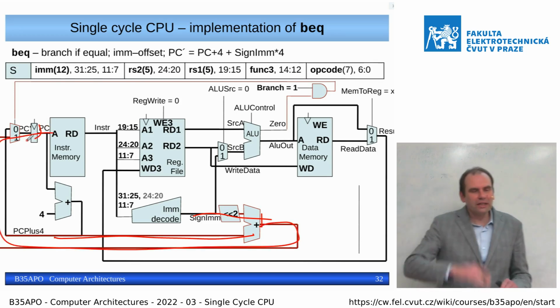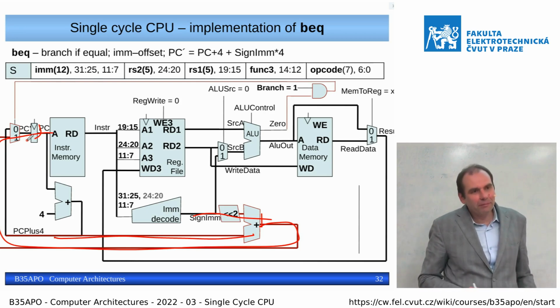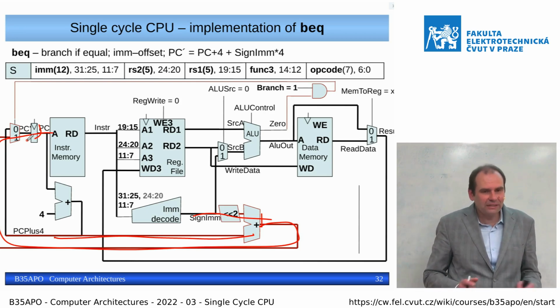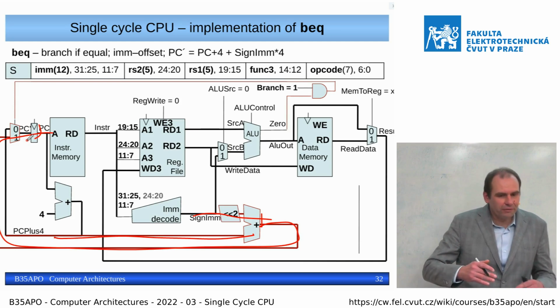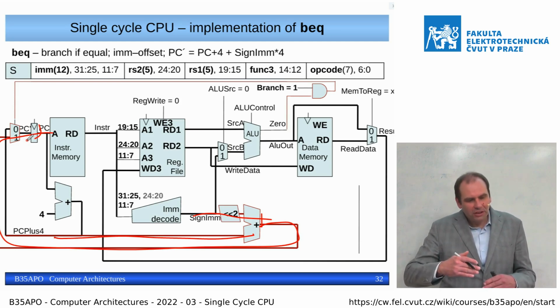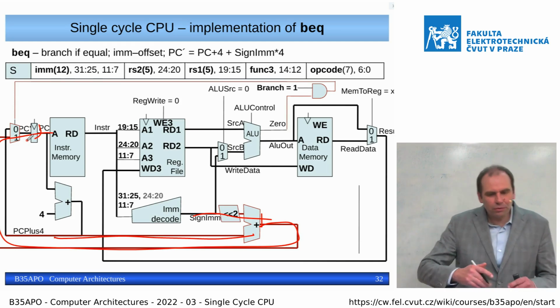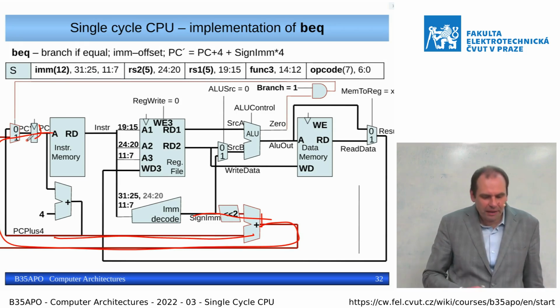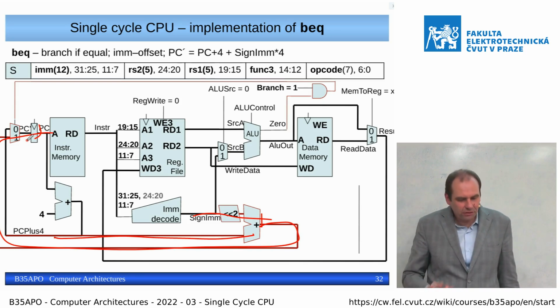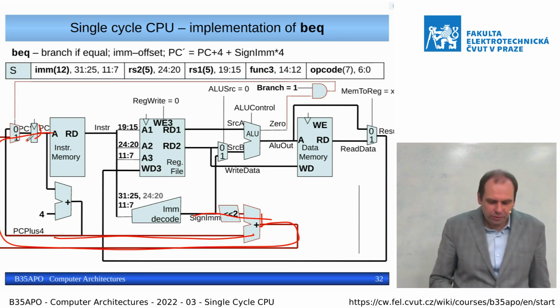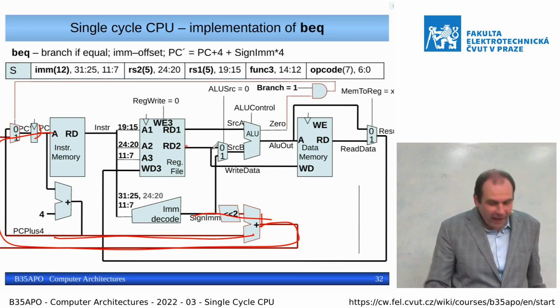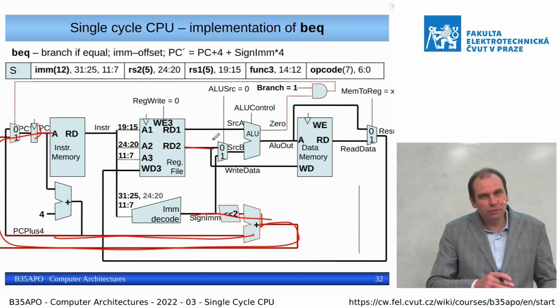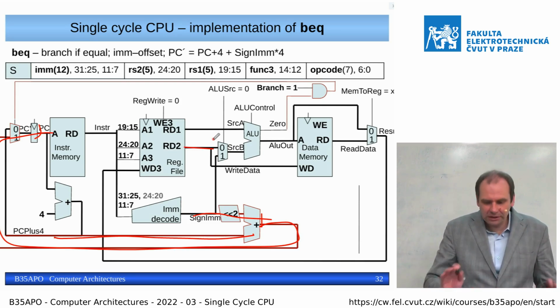So it allows us to branch in some range, like 4 kilobytes of the memory. If we have need for a farther branch, then we need to do a vice versa condition and put there some other branch instruction, unconditional, which allows bigger span, or we need to branch over a value which is read to the registers and so on.